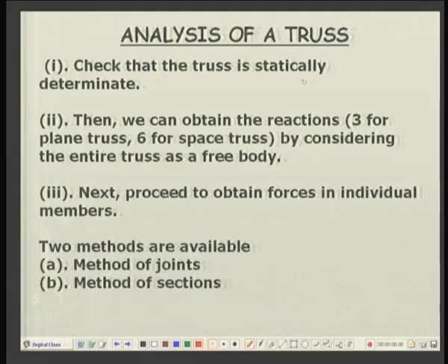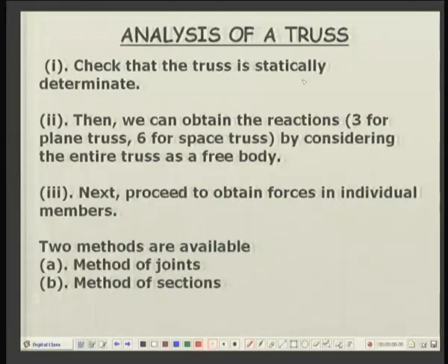After getting the reactions from the supports, we then solve for the forces in each and every member, or as required in a given number of members of the truss. There are 2 methods available for determining the forces in various members or elements of a truss. Number 1, method of joints, and the second is method of sections. So, we will start with the method of joints.